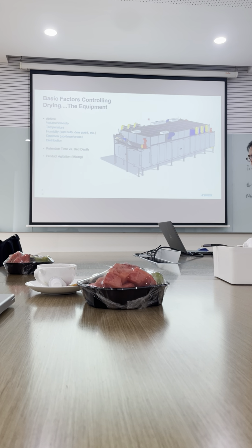From the equipment side, the basic factors controlling the process include the volume of airflow, velocity, temperature, humidity, direction, and distribution. The residence time and the bed depth are key factors.